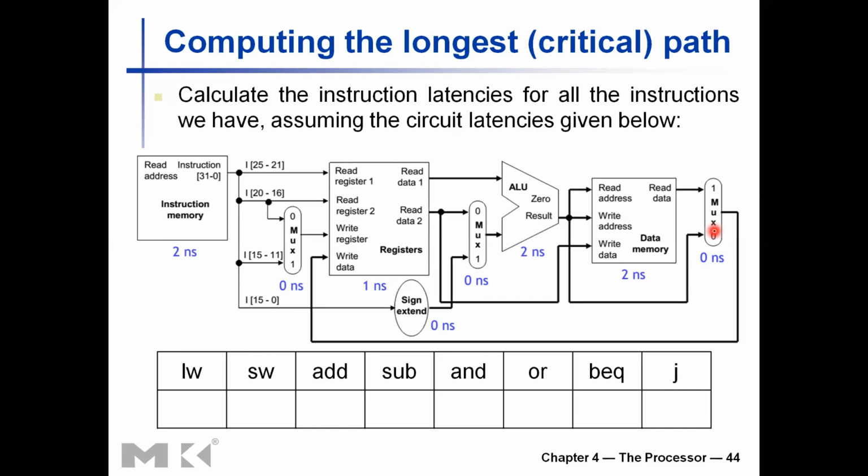So these are the major elements in the data path that will consume time. Let's assume the instruction memory reading will take around 2 nanoseconds, right? We said that the program counter gets updated at a positive, rising clock edge. From that rising clock edge, the instruction memory will take about 2 nanoseconds for the instruction word to change and get updated in the control unit.